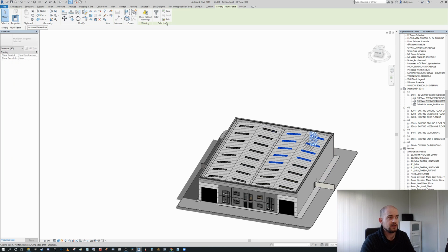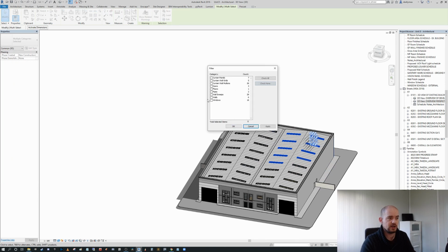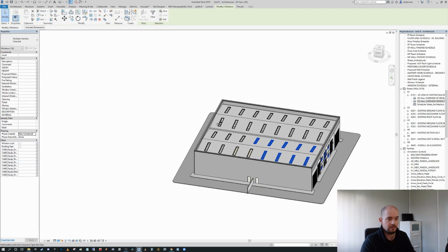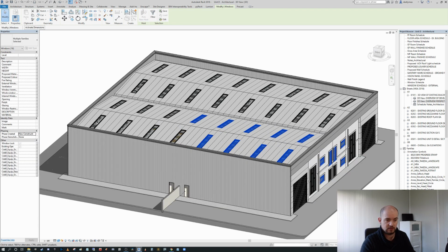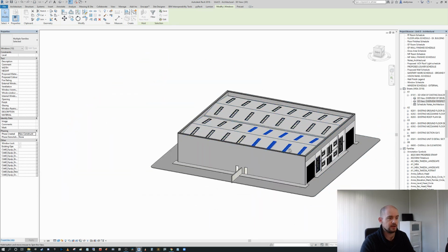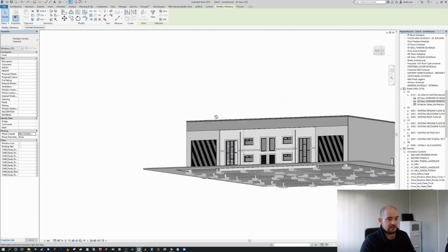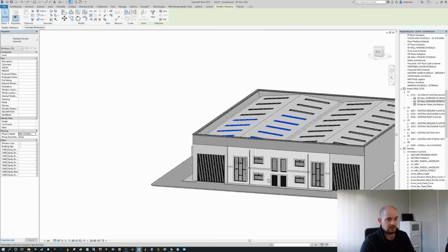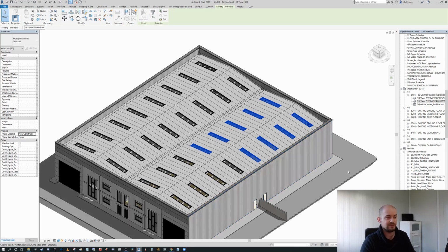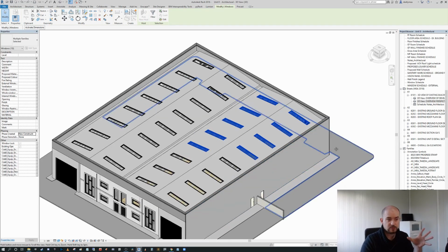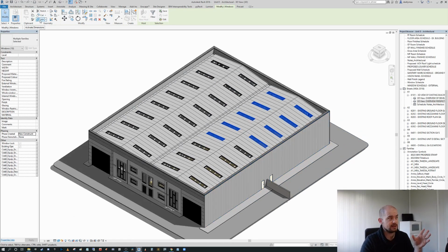Okay, so I'm going to use my filter as I did previously, and I'm going to check none, and I'm going to make sure that Windows is active. I'm going to press apply, and just on the inverse here, I'm just going to press shift and drag and remove those elements there. Okay, so we have a sum of 10 there. There's actually internal ones there, but I won't concern you with them for the moment. So we have our 10 elements there in our selection, okay?